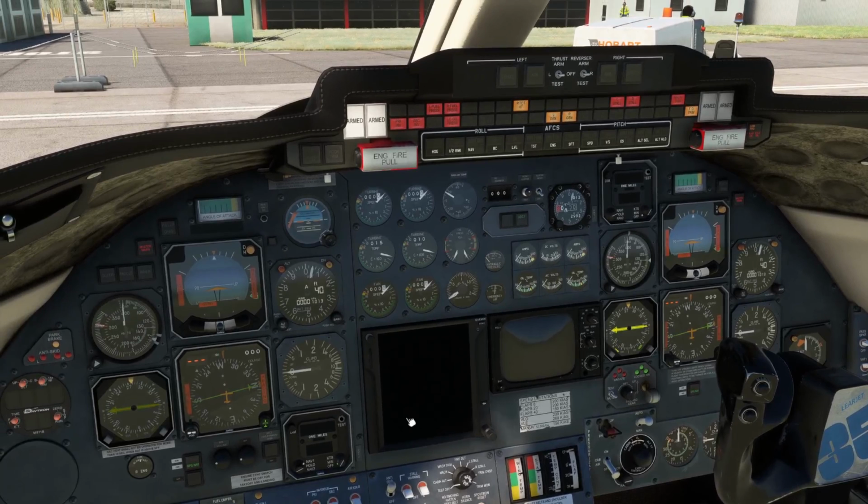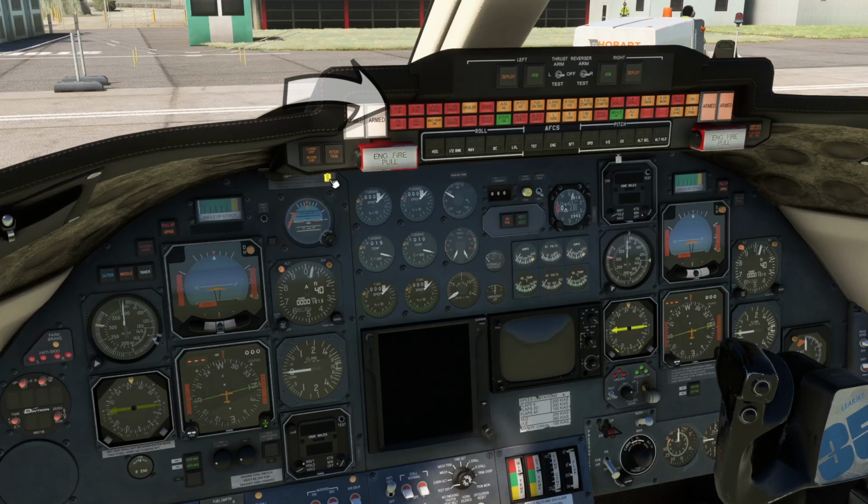So for example, if a current limiter was to fail, and now that we have aircraft power, I can show you. If I turn that on, and if we look on the top row of the annunciators on the far left, you'll see CUR LIM in red. If that illuminates, that means one or both of the generator current limiters has failed. The only way you can tell whether it's one or both is by monitoring the DC volts. If it's reading 28, then you know it's 1. If it's reading 25 or less, then you know both current limiters have failed and you're just on battery power.